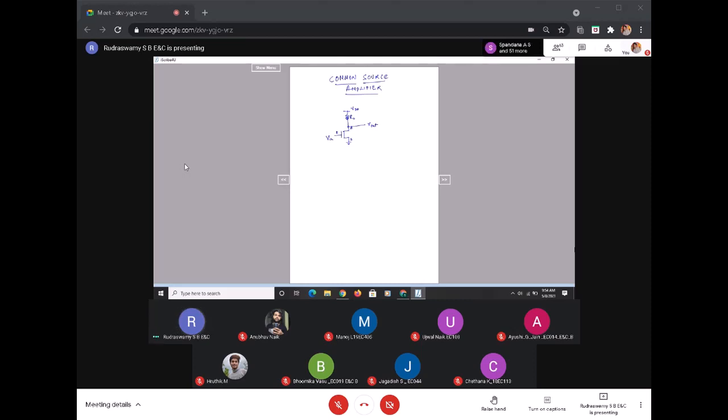As I said before, even if you have the passive device resistance, in an IC, realizing this passive device resistance or the capacitors occupies more space and more area. That's one disadvantage. The second disadvantage or drawback of using these passive devices is that it dissipates heat. That's why we have to use some dynamic resistance or an active resistance in order to overcome the occupancy of more area and also this heat dissipation problem.